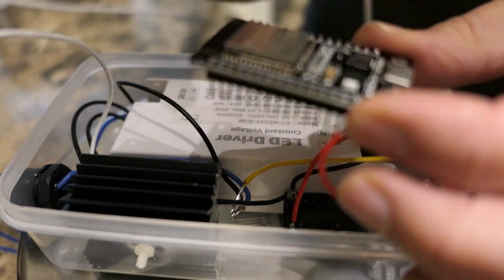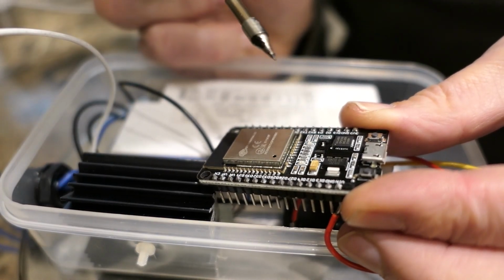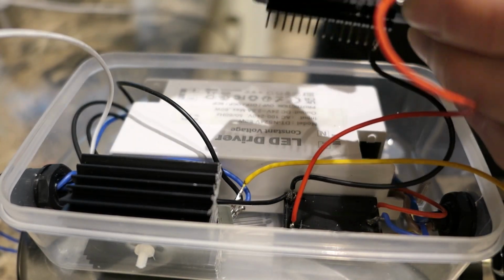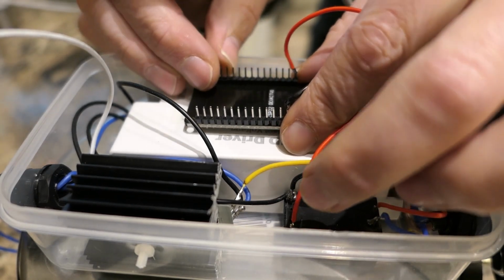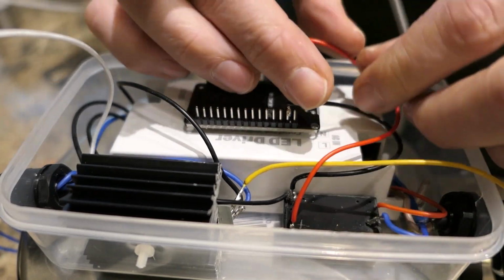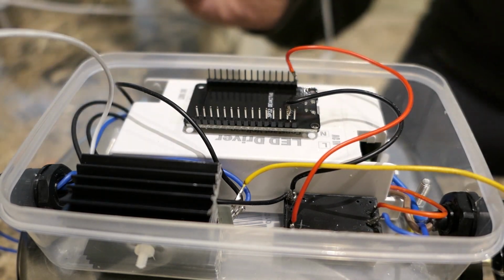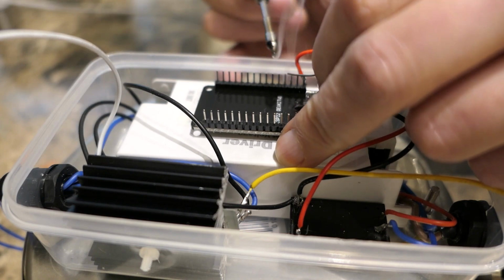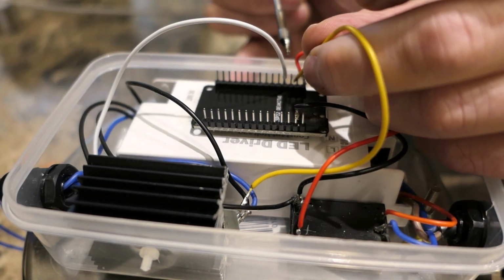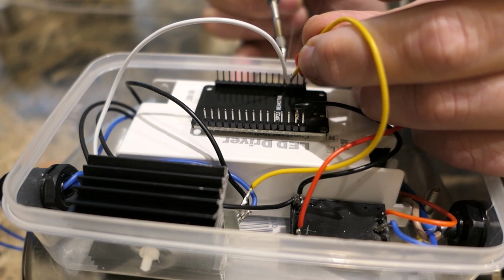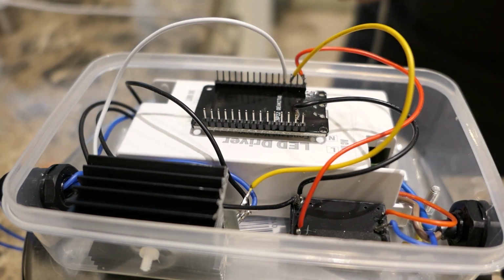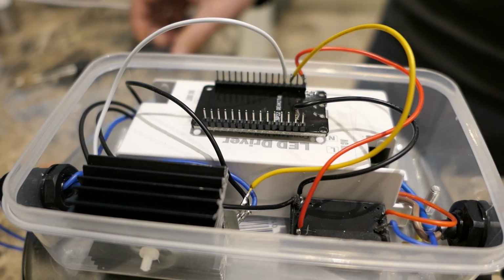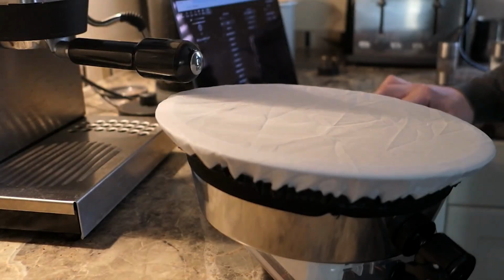But the one thing you haven't seen me solder so far was the ESP32, because I actually forgot to take it to the lab that day. So here I am at home. I've got my ESP32 and I'm going to mount it directly on top of the 24 volts DC power supply. So I'm just going to use double-sided tape. And if you think about it, there's actually only 4 wires that need connecting to the ESP32: the 5 volts, the ground, and the 2 outputs that go to the MOSFET gates. So once that's done, it's ready to configure the software, which can be done wirelessly.